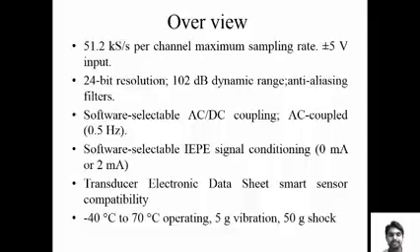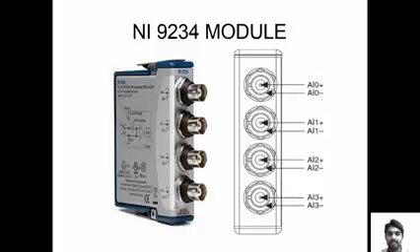Transducer electronic data sheets (TEDS) sensor compatibility, and also minus 40 degrees Celsius to 70 degrees Celsius operating, 5 g vibration, and 50 g shock.